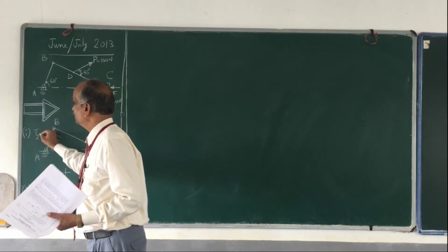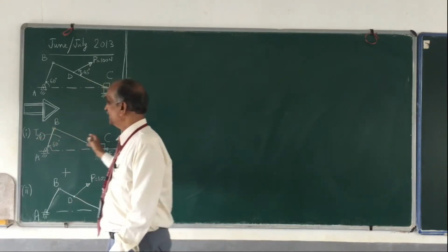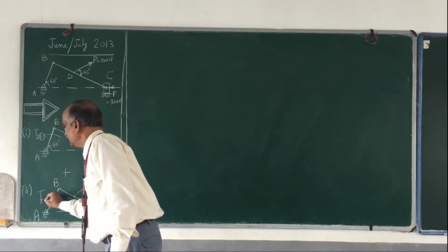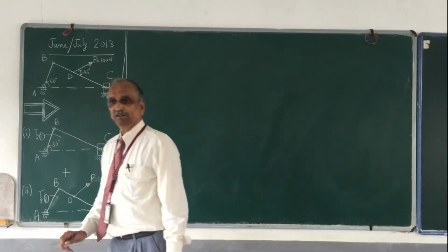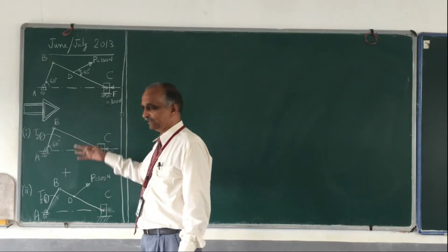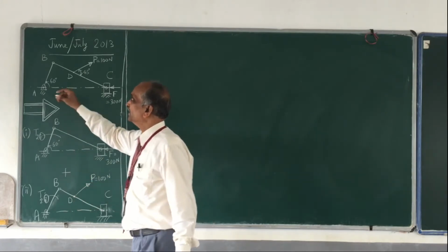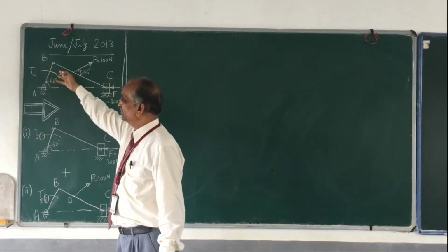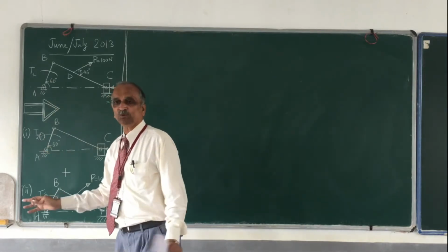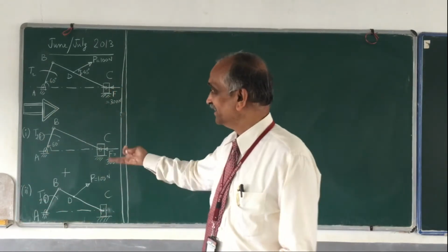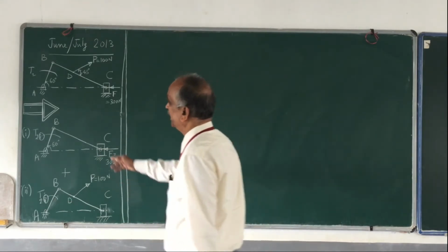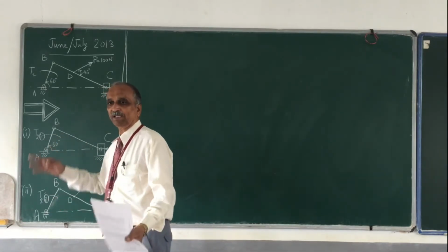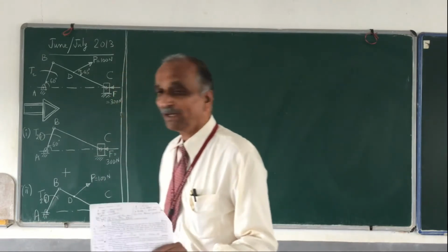And if I add these two, then find out the torque, let me call this T21, the torque required for the first problem. And similarly, let me find out the torque required for the second problem. If I independently do this and then add, I shall get the T2 which has been asked in this problem. T2 is the sum of T21 plus T22. Of course, the magnitude and directions also have to be taken into account when I add T21 plus T22. If one is clockwise and the other anti-clockwise, then one of them has to be taken as minus, and that is how I have to find it out.